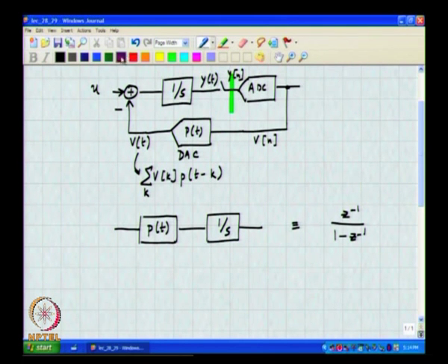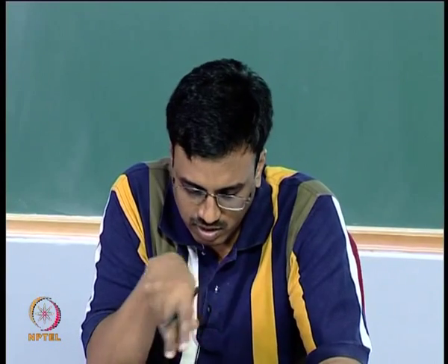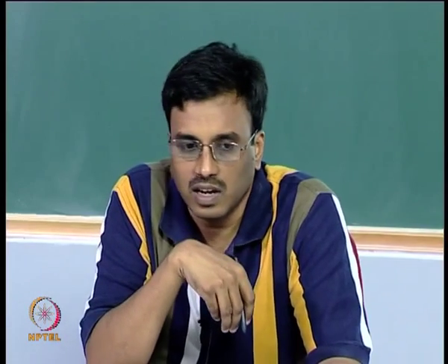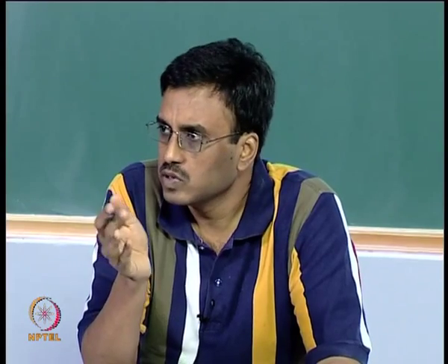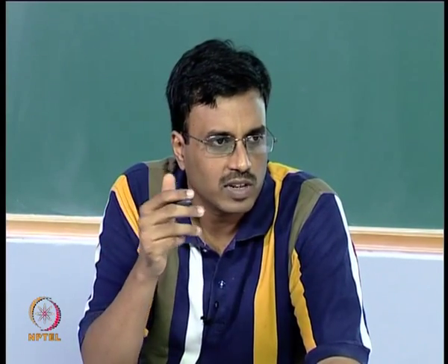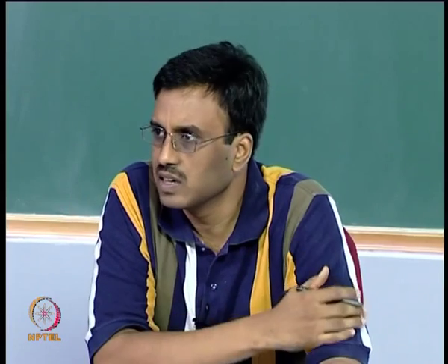a pulse shape P of t being the NRZ pulse, and I would like to remind you again that the sampling rate is normalized to 1 hertz. You can always take the values of the components in a 1 hertz normalized schematic and scale them so that it gives you the same noise transfer function at some other sampling rate.